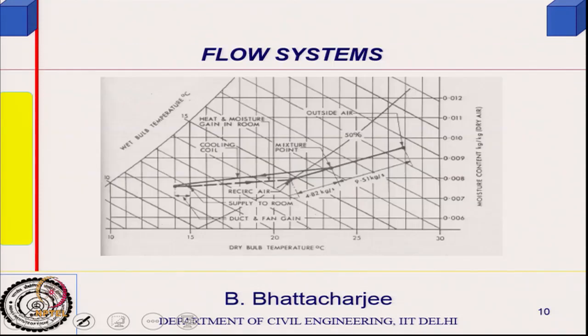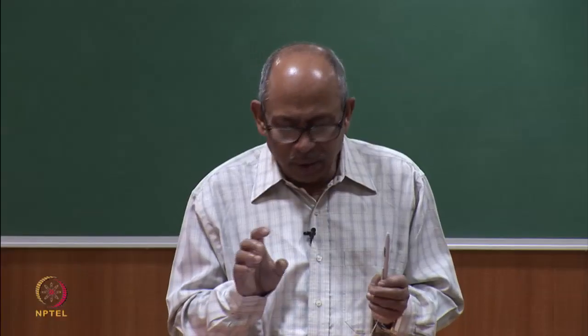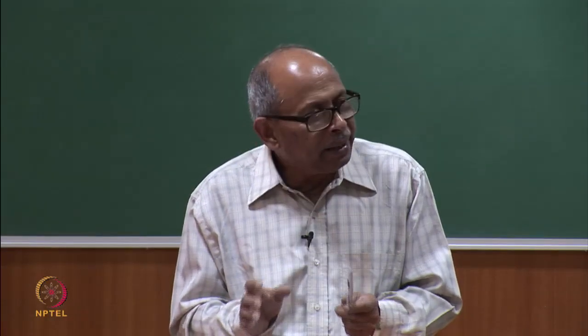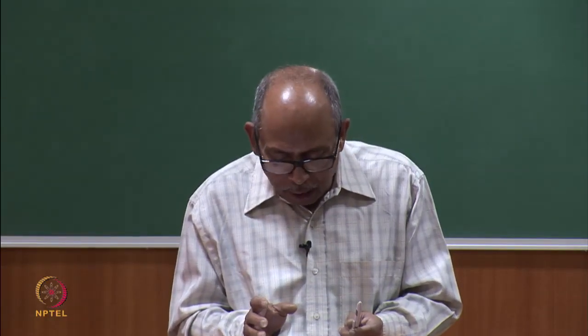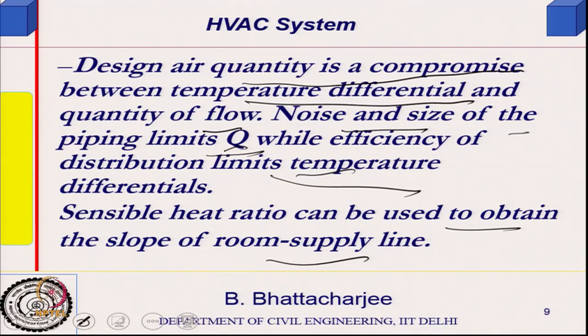So this is basically the guideline. The idea is why and how we keep the temperature differential fixed, and why you keep the temperature differential fixed first to find out the flow rate, and then estimate the supply temperature and supply moisture content.